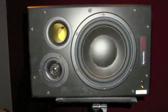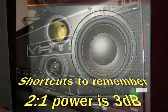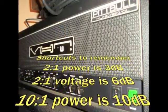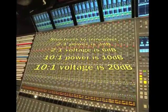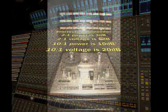There are 4 shortcuts to remember. A 2-to-1 power ratio is equal to approximately 3 dB. A 2-to-1 voltage ratio is equal to approximately 6 dB. A 10-to-1 power ratio is equal to 10 dB. A 10-to-1 voltage ratio is equal to 20 dB.